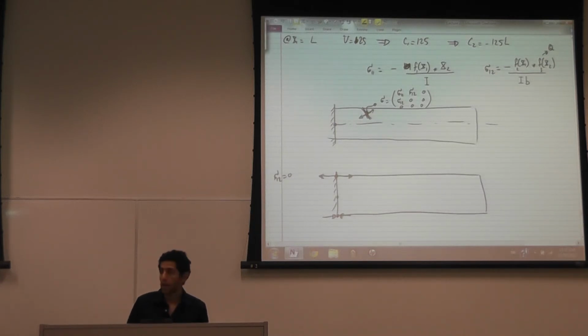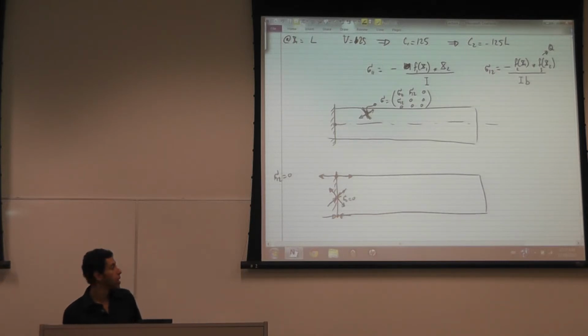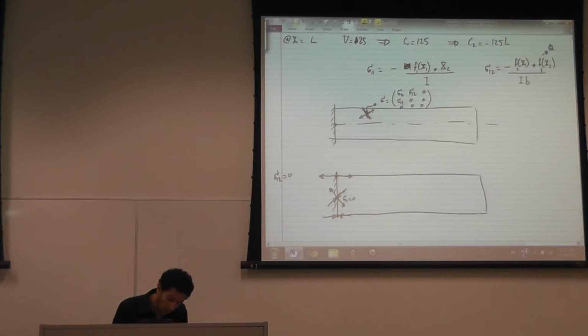In the neutral axis, you have sigma on 1 is 0. But you have the maximum shear stress. And so right in the neutral axis, you'll find that there is another coordinate system, perhaps this, yes. This will be tension, and this will be compression. So in this coordinate system, the stress is diagonal, and so you've got tension in this direction and compression in the other direction.